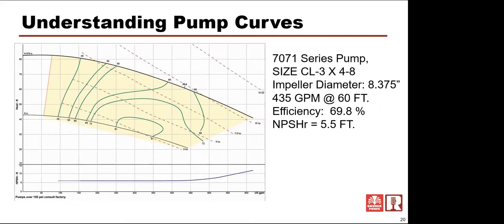So at that particular point, down at the bottom of this curve, we have what's called an NPSHR rating. NPSHR stands for net positive suction head required of this pump. In other words, that's what pressure on the inlet side of this pump needs to be able to fill all of those impeller vanes full of fluid without any kind of air pockets or cavities or voids.